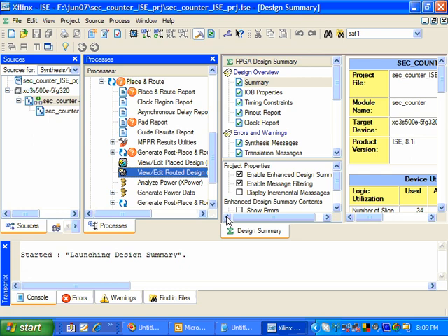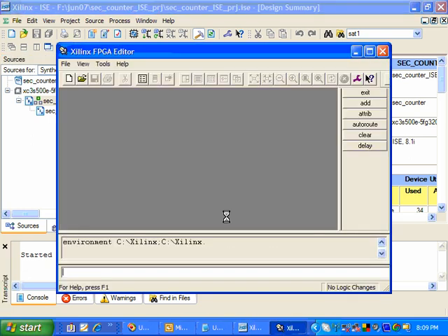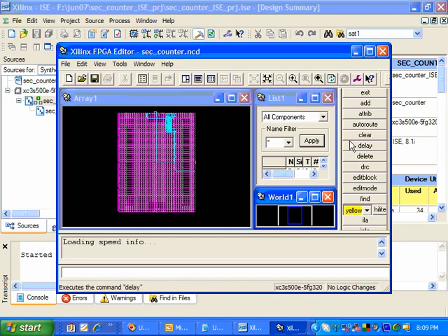So the logic cell concept that you have seen is fundamental, but today's modern FPGAs come in different ways. If you see a Spartan 3 FPGA, it has one CLB with 4 slices. Each slice will have, like what you have seen in the block, 2 lookup tables and so on. That's how they manage it. They call them slices, 4 slices. Okay, now let's see this.